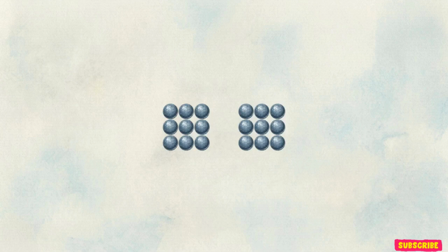To change its electrical properties, we introduce specific impurities. By adding boron atoms to one side of the lattice, a process called p-type doping, we create localized electron deficiencies. These empty spaces are called holes, and they act as positively charged carriers within the crystal. On the opposite side of the lattice, we introduce phosphorus atoms. This is n-type doping. The phosphorus provides an excess of free, unbonded electrons, creating a surplus of negatively charged carriers.